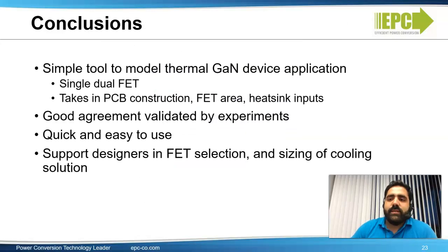So in conclusion, we presented a simple reduced model and a thermal estimation tool for GaN devices. We did the analysis for different size FETs in single and in dual configurations with different PCB constructions and cooling setups. This tool is also compared to experiments and shows good agreement with the observed measured results. And the tool is packaged in a user-friendly interface, which is quick and easy to use and can support engineers in FET selection for their specific application and also to size cooling solutions if needed.